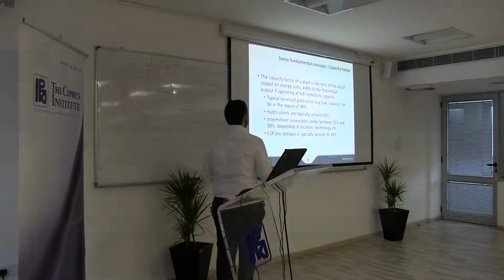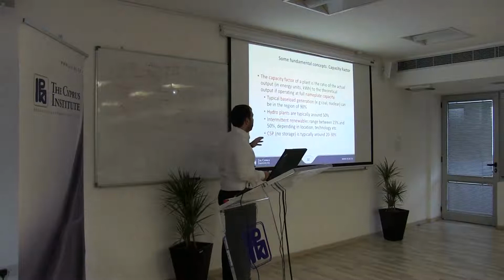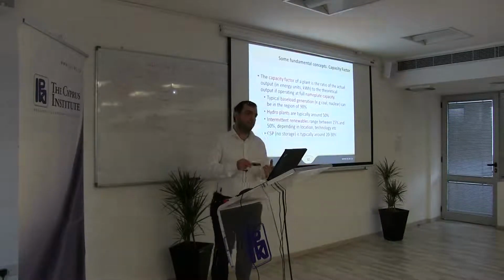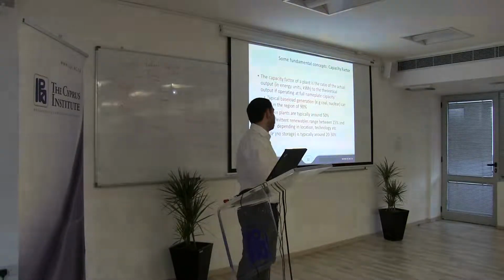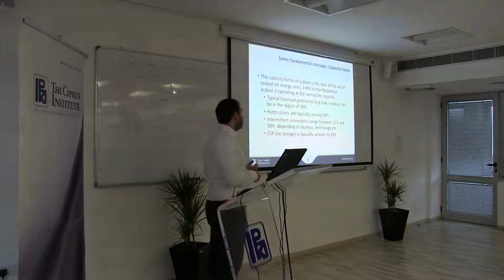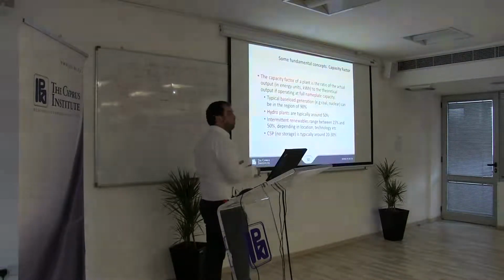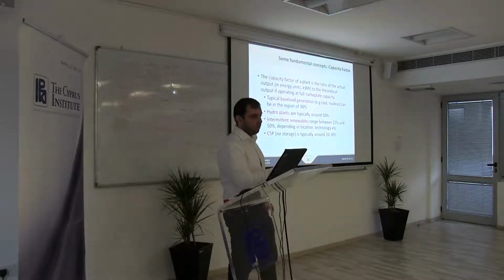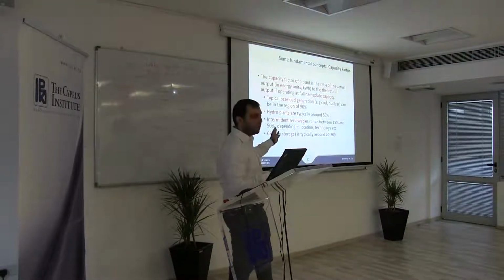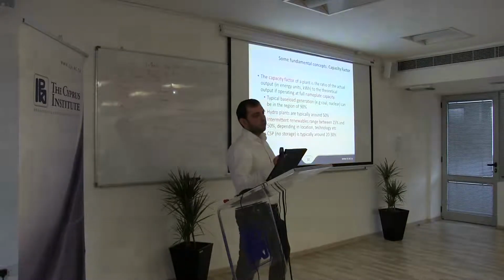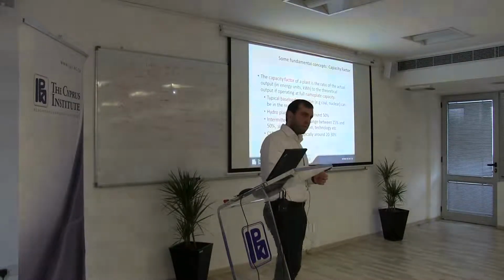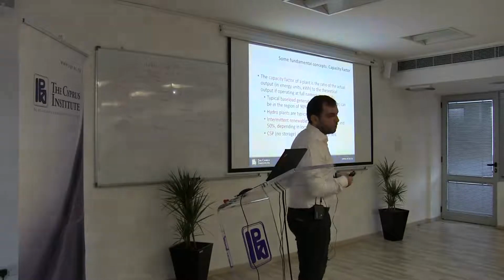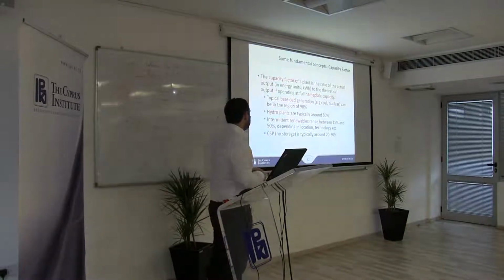In the case of hydro plants, a general number is around 50%, but this is highly variable. There are hydro plants that have dams that might have a much higher capacity factor. There are hydro plants that have no dams, but they have a constant flow of water that doesn't decrease over the year. There is no seasonal variation, so it might be higher than 50%. Or there is the seasonal variation of rainfall, for instance. If there's a dry period in the country, it will decrease the capacity factor, so it might be lower. So it's very, very location specific.